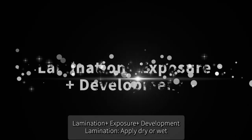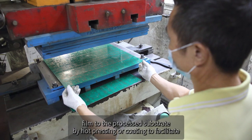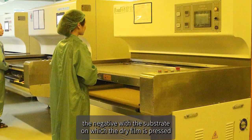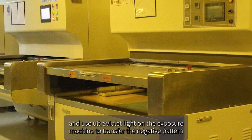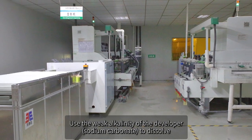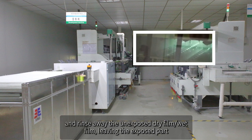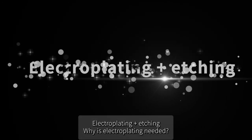Lamination plus exposure plus development. Lamination: apply dry or wet film to the processed substrate by hot pressing or coating to facilitate subsequent exposure production. Exposure: align the negative with the substrate on which the dry film is pressed, and use ultraviolet light on the exposure machine to transfer the negative pattern to the photosensitive dry film. Development: use the weak alkalinity of the developer, sodium carbonate, to dissolve and rinse away the unexposed dry film/wet film, leaving the exposed part.